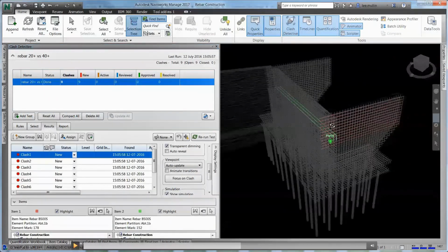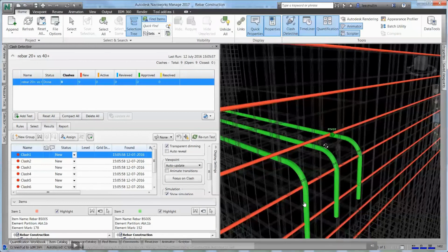Okay, what you're seeing there, it's a clash detection done on rebars. Obviously, this can be done on steel connections as well using Navisworks. And this type of detail, it's very difficult to check inside of Revit and Advanced Steel, but using a tool like Navisworks, which picks up the components from either Revit or Advanced Steel, we're able to run clash detections and manage the reporting as well from this, right? If you look in there, you'll see the clashes between the two rebars on there, right?